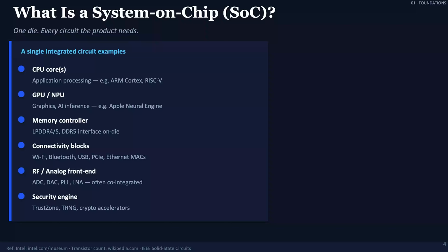That does not mean the whole phone is one chip. In practice, a smartphone usually includes multiple chips or companion SoCs for functions such as main processing, cellular connectivity, Wi-Fi, and power management. The main SoC, the central computing engine, integrates functions like CPU, GPU, or neural processing units.